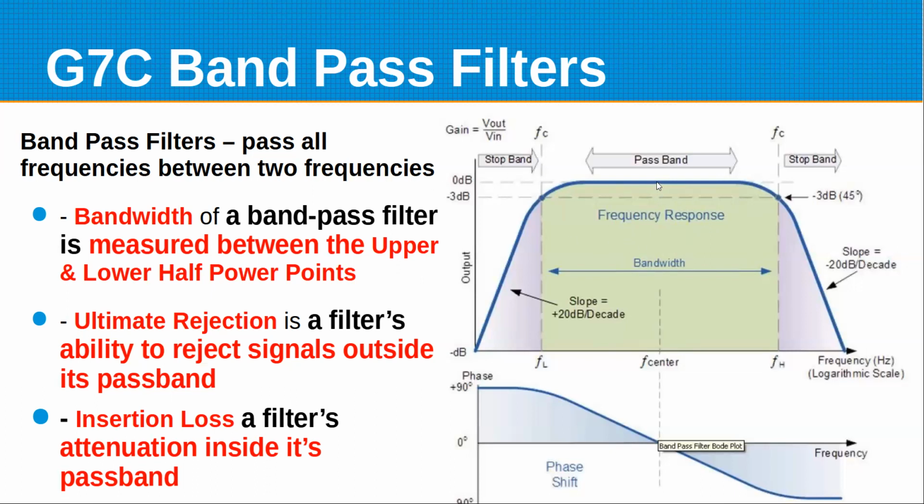It's just relative to the pass band of the filter. So you may have 1 or 2, 3 dB insertion loss on the filter, which is another reason why a lot of times they will use active filters. So they actually have active components, amplifiers in them to compensate for the loss.